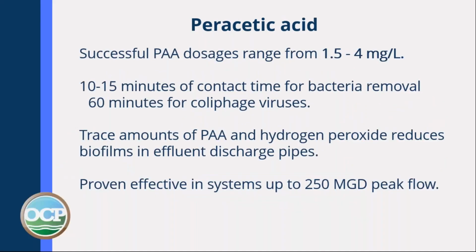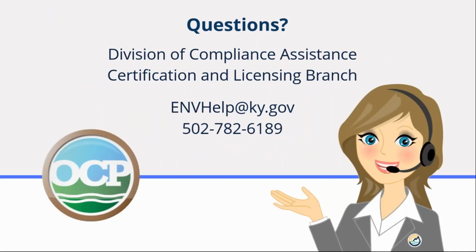One of the other advantages of peracetic acid is that the supplier you order the peracetic acid from, for most small systems, will supply the pump and skid setup that's needed. And then they'll come and service that every time they come to check on the PAA supply. So most of the systems in Kentucky that are using it really like it. And that's the end of disinfection.